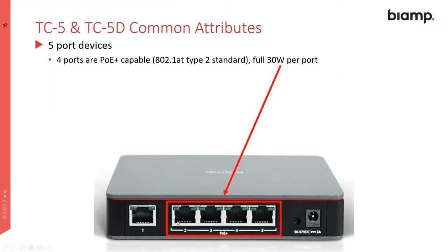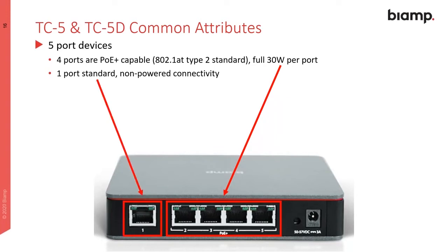Remember that ports 2 to 5 are 802.3at Type 2 standard, which is capable of a full 30 watts per port, so you can drive a 30 watt PoE Plus device. Port number 1 is a standard port, non-powered connectivity.